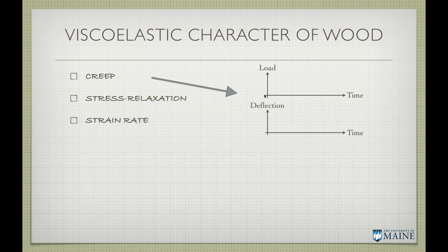For creep, we plot load versus time and deflection versus time. At some point in time we put a load on it, the load is constant, and we take the load off. This would be the standard loading situation for a creep test.